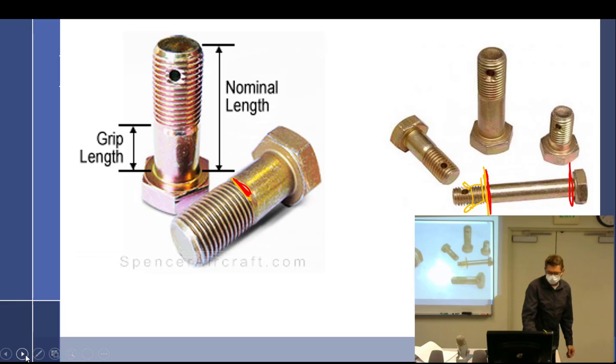Well, what if I got a bolt that was made on a Friday when everybody was trying to get out of there, and it's a little bit too small, but I use it in that wing fixture? What's my wing going to do? Vibrate. It's going to bounce back and forth, and as it does that, it stresses out the bolt every time it moves. And eventually it might shear that bolt off or work the hole bigger. Hole gets bigger, the wing's all slop. I mean, nobody wants a wing that's bouncing back and forth, right?